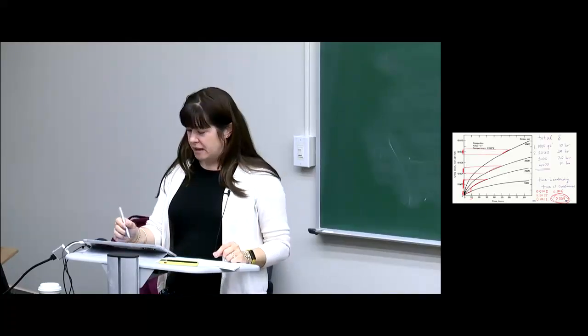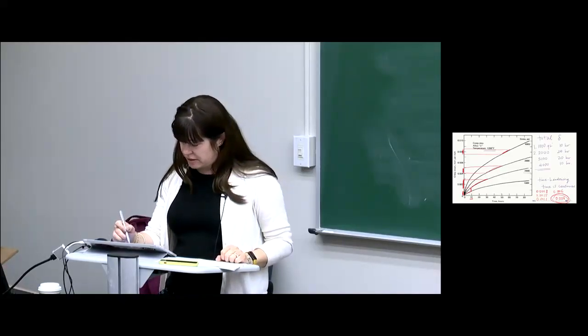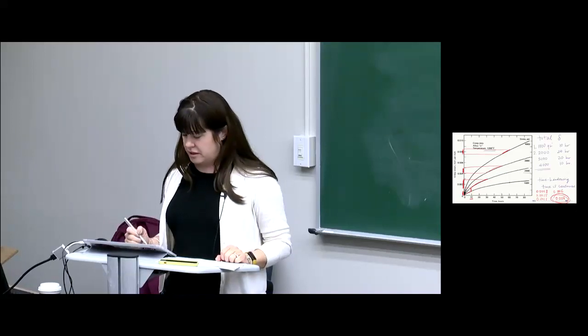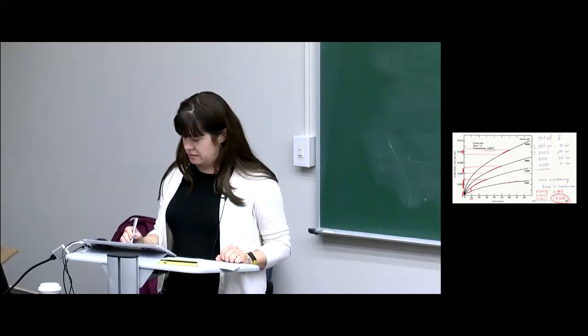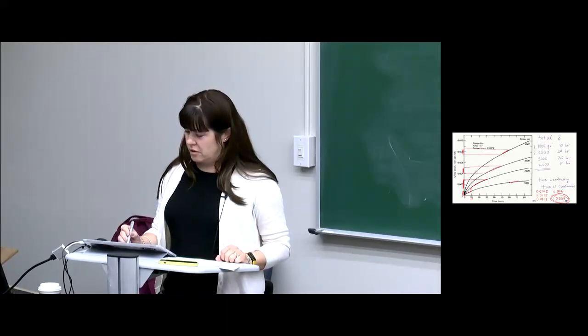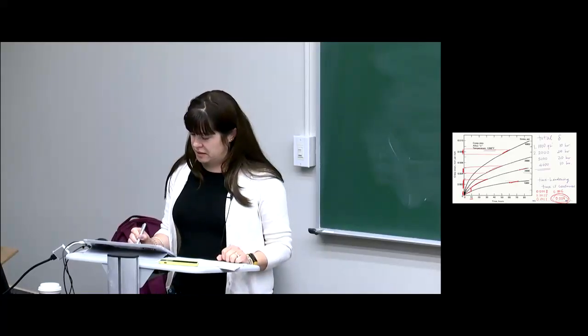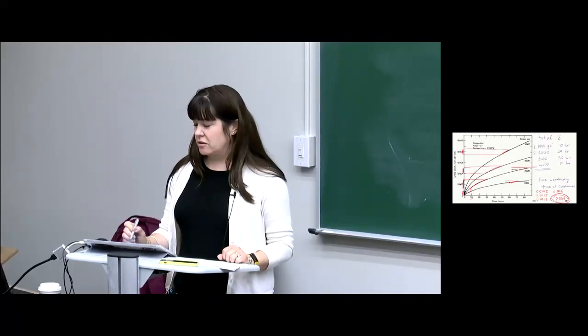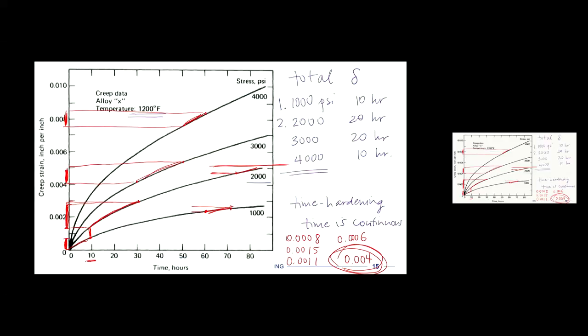right? So if we go back, I just want to continue on because it's an important question. So now at 60 hours, if we go back and we start another cycle at 10 hours, see how the creep strain drops off there. So at some point, it's going to kind of diminish down to 0, right? Because now it's like tiny, tiny increments. So you can't assume each cycle is the same? Yeah, so I'm going to take back what I said, right? If you were doing a super conservative analysis, you could say that each cycle is the same. But because these are logarithmic curves and they drop off the further you go up, then at infinite number of these thermal cycles, the increment of our creep is going to drop down to 0.